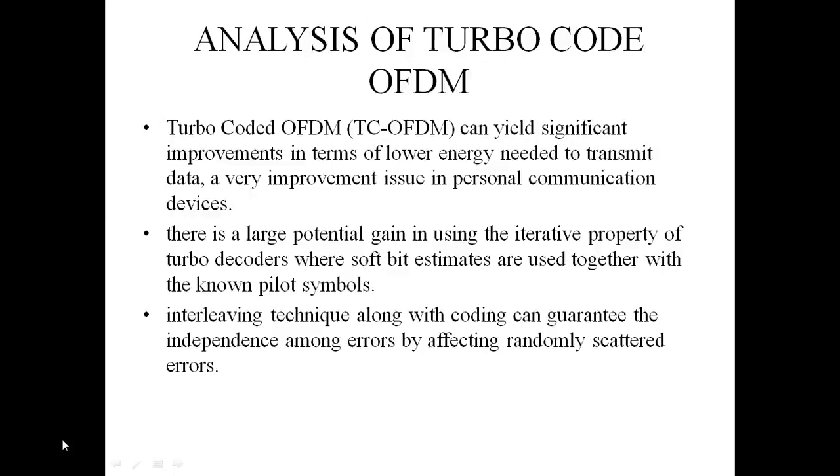For the analysis, we make use of the Viterbi algorithm, which is used for decoding the convolutional codes. This makes use of the decoding trellis, which records the state of the encoder at a set of time instants. This works on the principle of rejection. The algorithm works by rejecting the least likely path at each node of the trellis. Now what is left is a single surviving path which is kept behind.